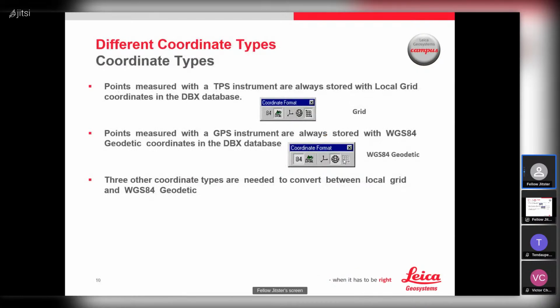And why do we need to do this? Typically, instruments such as total stations perform measurements of angles and distances, which means that they work in some kind of horizontal system, and basically with some vertical heights. And GNSS works in this XYZ Cartesian geocentric system. So in order to combine these different measuring devices and methods, you need to know these parameters, how to convert the coordinates and transform.